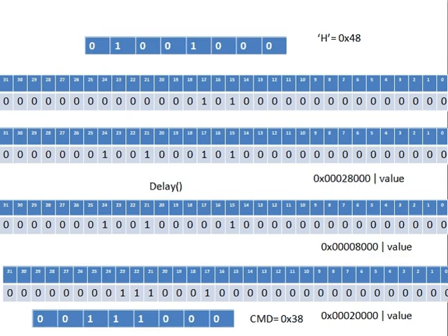Now when you observe this register content, port 1 15th bit is made 0, so implies that you are passing command, and port 1 16th bit is also made 0, which means you are writing a data, and port 1 17th bit is made 1, which means this is your enable line. So you have 2, so 0 to 17 and remaining bits are all 0. That is ORed with data which is having data beginning from 18 to 25, you concentrate, you have a data, and remaining values are made 0.